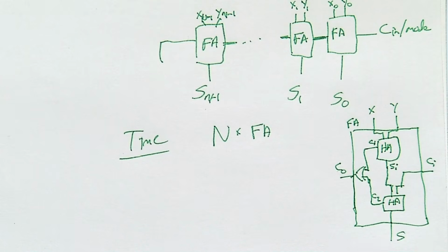If I had put CI into this one here in place of, for instance, I, then you have to go through this one and its output into this one. Each of these numbers, if you remember, there's two gates to each. So it takes one gate, and since I'm worried about my propagation from here to here, CI to C out, the thing that slows you down, okay? So I end up with 2 gate delays between this. That's the best you can do.